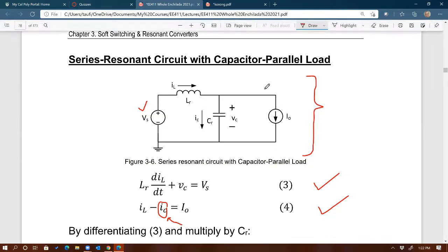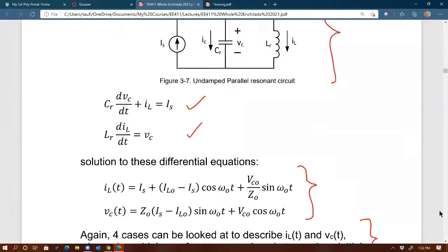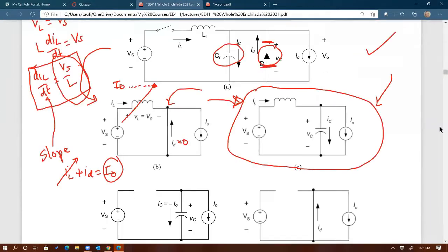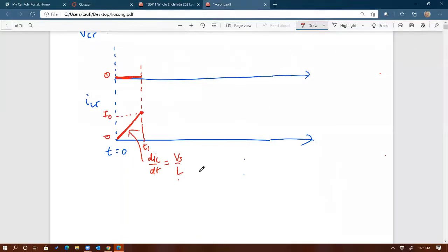And what can we know about this circuit from the previous section? What can we know if you have this circuit? That inductor current will be what? Sinusoidal, as well as the capacitor voltage. Exactly. That's why, to me, this is really clever, because as soon as the diode is off, naturally the circuit changes its state to a resonance circuit. Cool, huh?